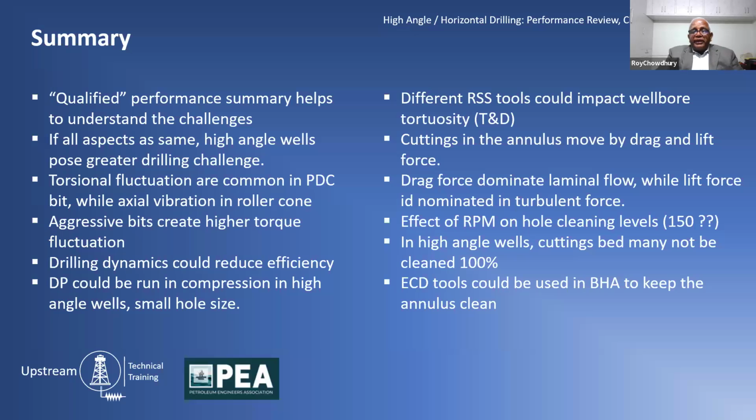I'm sure everybody rode a cycle or motorbike. Remember the speed breakers. When you see a speed breaker, you slow down. In this case, you haven't seen the speed breaker because it is 3,000, 4,000 meters down below. So the first thing that you do is de-energize the drill string. Slow down your RPM. When you slow down your RPM, you are already helping your gauge cutters. Remember those gauge cutters, they are spinning with a very high work rate.